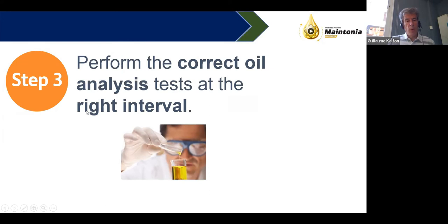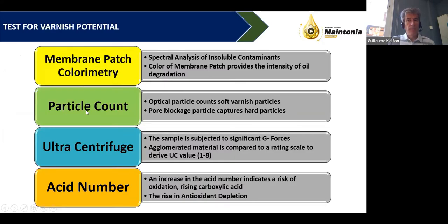So a very important part of that is oil analysis, which you will get on most machines. Some machines don't get any oil analysis. Maybe sometimes it's right, maybe there's no need. Some machines need it and they don't get it. So in that case, it should be implemented that the oil gets sampled on a periodic basis and gets analysis.